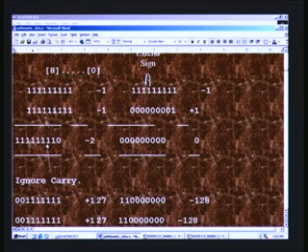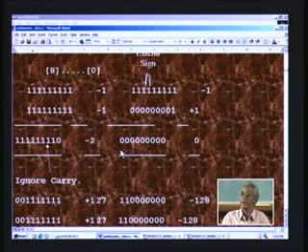Okay, this need not be done, we are just merely adding here. We will see this is the MSB sign bit, so minus is there, and the first one we encountered is this here, and we retain these 2 bits and make the other bits 0. That is the shortcut notation we have already seen. So this is nothing other than all zeros 1 0, which implies 2. So the magnitude is 2, that is what we put here, and similarly you can put for all these things. -1 1. If you add the 2, it is mere simple addition without regard to any sign.